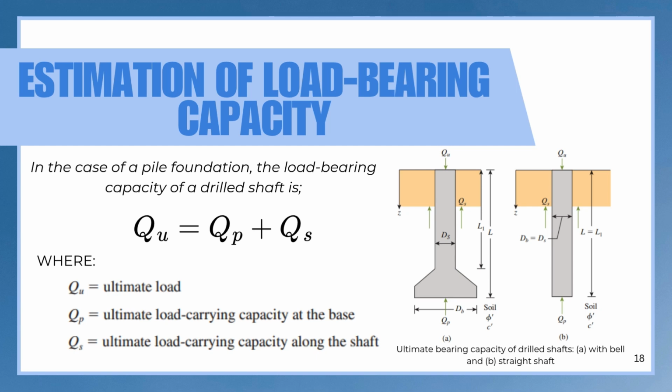However, a straight drilled shaft has a uniform diameter and carries load through both skin friction and end bearing. With skin friction often being significant, it is simpler and more economical to construct, making it suitable for soils with good side resistance. This type is commonly used for moderate load structures such as residential buildings, commercial buildings, and towers.